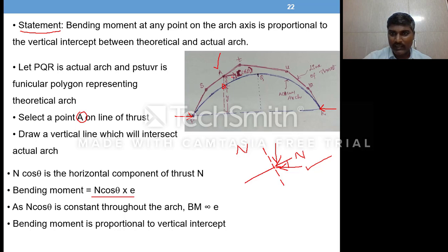As there are no horizontal forces externally acting on the arch, because the loads are taken as gravity loads, which are always vertically downward, the only prevailing horizontal forces are the support reactions, and they are equal in value, because sigma Fx = 0 must be satisfied.